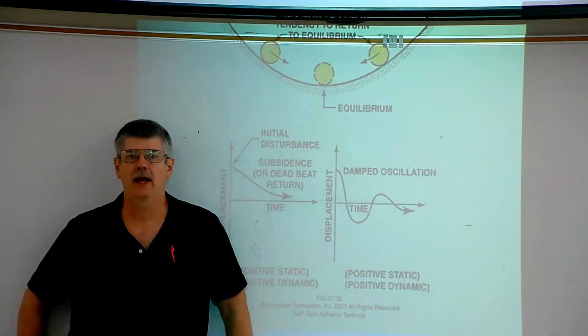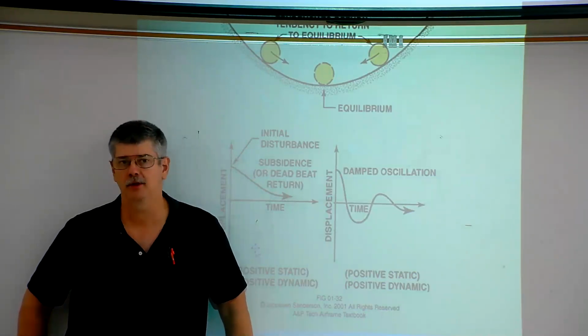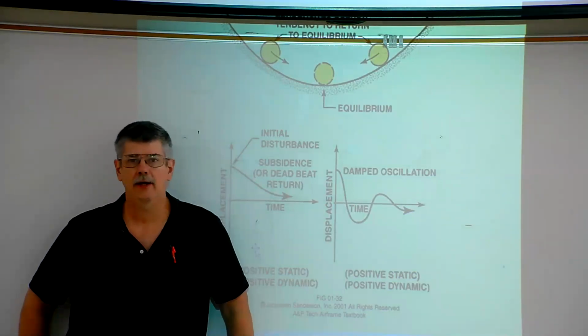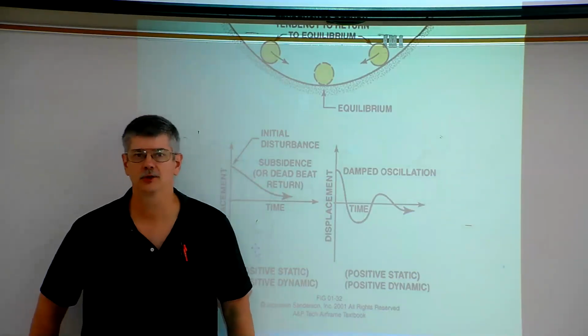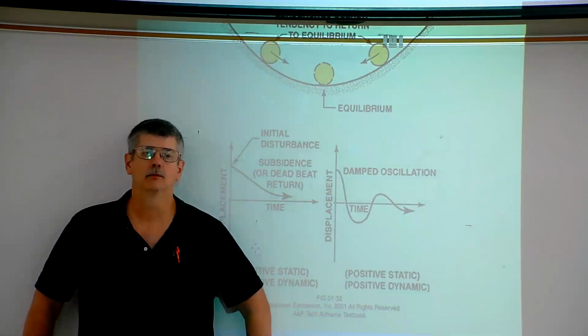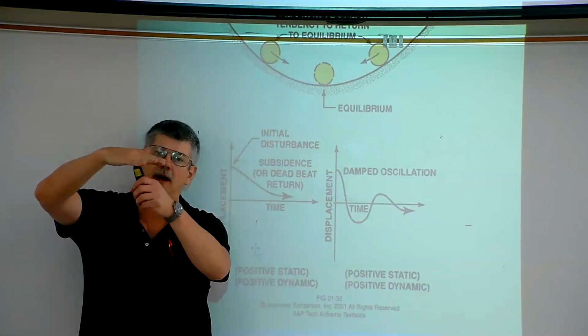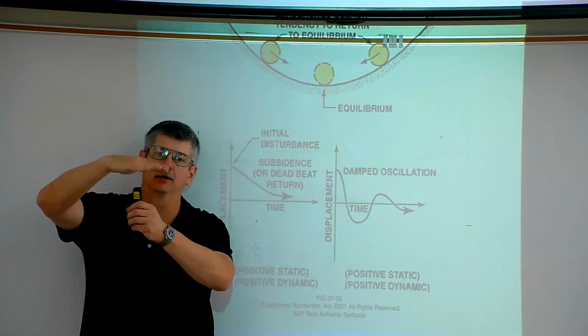We said that low-wing aircraft require a greater dihedral than, say, comparable high-wing aircraft. The high-wing aircraft doesn't need such a large dihedral for two reasons. Number one, what is known as the pendulum effect. With a high-wing aircraft, we have most of the weight underneath the wings.